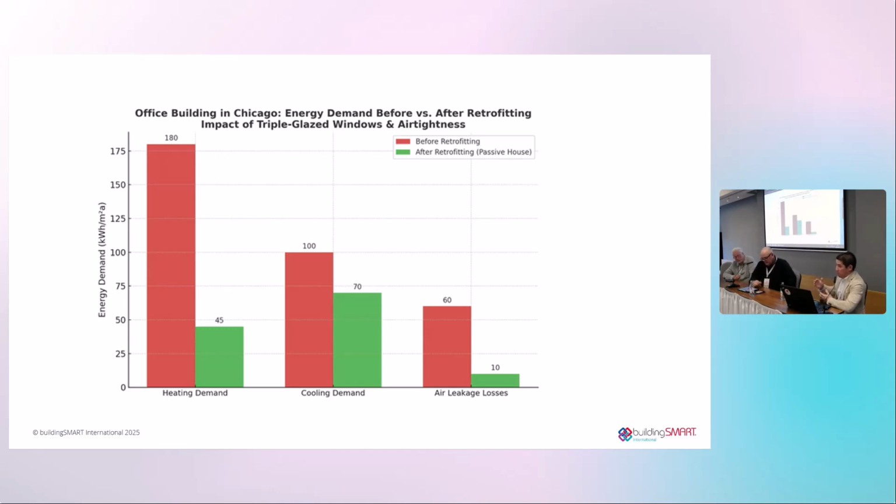Based on my master's thesis in the past, air tightness alone affects 9% of whole building energy demand. So 9% means even if you only improve the air tightness, you already win 9% energy efficiency. Now calculate the window. You have no more thermal bridging there. You have improved layers, and of course it's more airtight. So that's a reason.